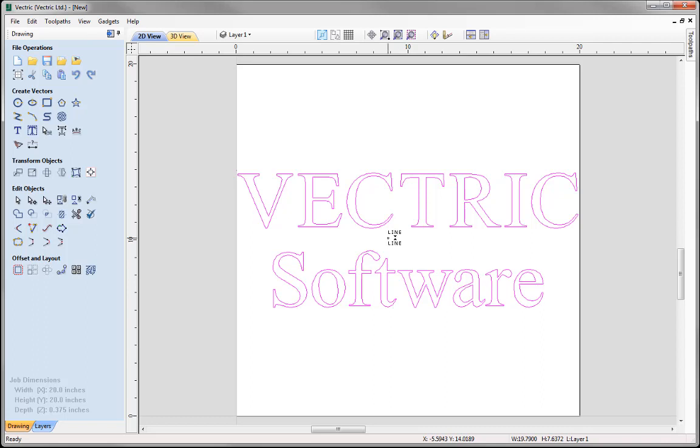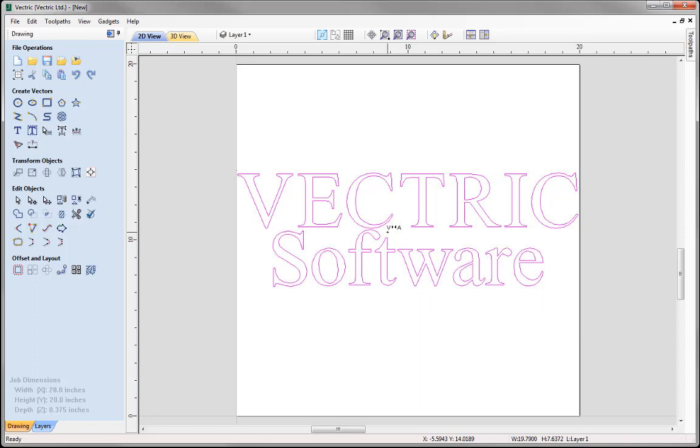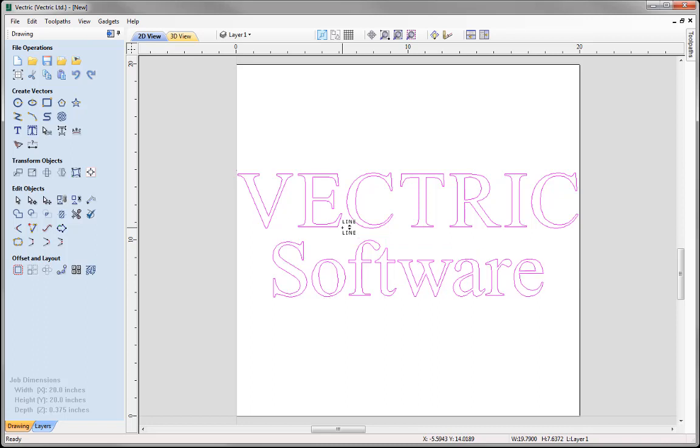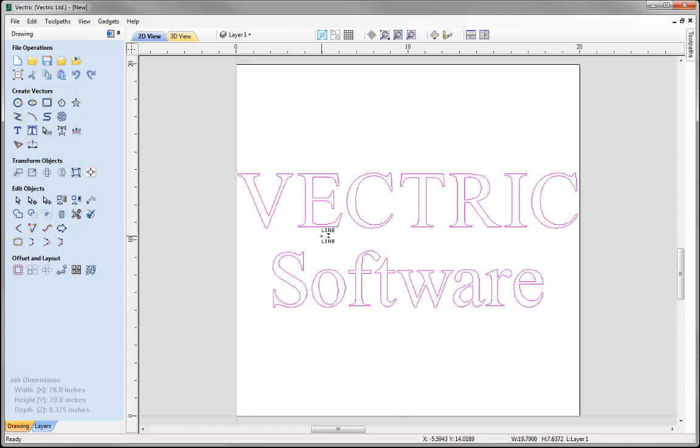And the same applies again if we hold down Control. I can decrease that spacing in bigger increments by holding down Control whilst I click, like so. And then we could do the same to decrease the space between the lines. So I'm just going to hold down Control and Shift just to change that direction, and I can just click and increase the space in there. And so you just increase or decrease the space in between the characters, between the lines, until visually it looks better.